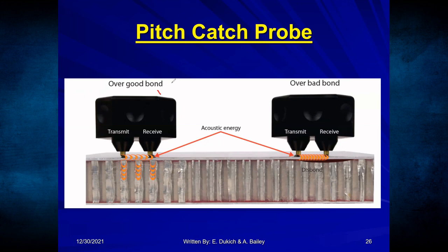So on my left side, this is called a pitch catch probe. It transmits sound into the material. And so you see the sound traveling through the material, but it only goes so far. So if I lower the frequency from 100 kilohertz down to 5 kilohertz, I may actually be able to penetrate the backside.